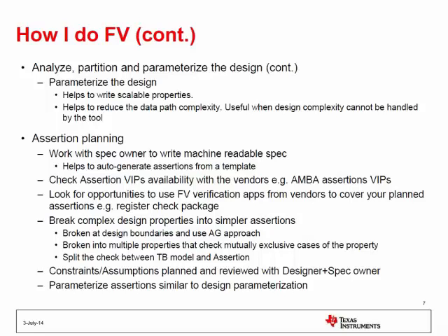So why do I need to do parameterization? Because the tool sometimes will give up, saying we are having a huge number of things. That's what I think we saw in the IBM presentation, right? The tool gives up, but to handle it, you can parameterize the design and say, okay, instead of having 32 bits, I'll try with 16 or 8 or 2 bits, and you'll see that your property is still being proven on the complete design.